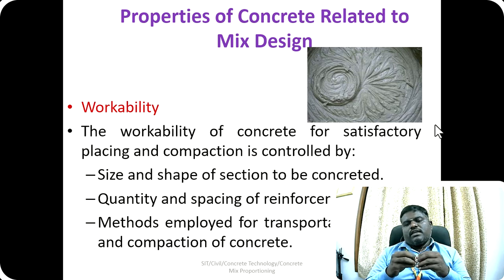So if the time duration between the batching plant and the site is more than 30 minutes or 40 minutes, then the cement will start to set. So during that time, we have to ensure that for the 30 minutes or 1 hour, the setting of the cement is not completely done, so we will add some extra admixtures.